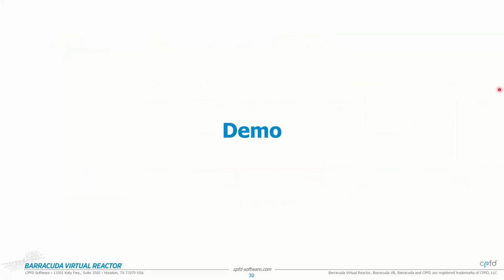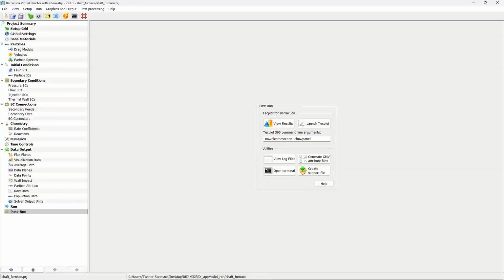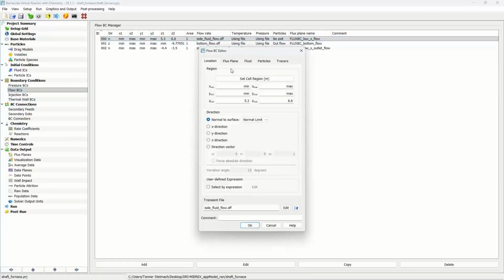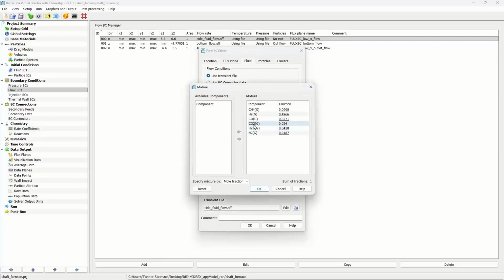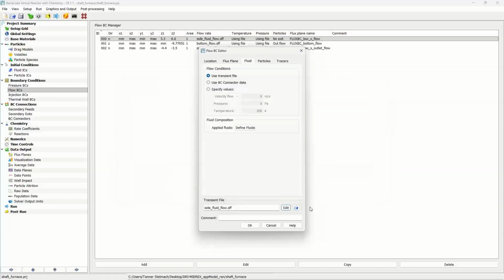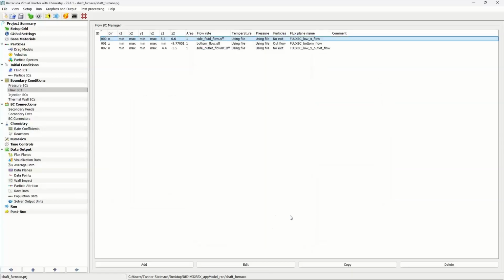Right, and I wanted to quickly show, for this system, in order to adapt the model we currently have on this application model post to operation as a shaft furnace, you could come here to this system and we can make adjustments to the actual composition. So for those tests, we use 100% hydrogen. This mixture mole fraction can be changed to 1. And you can also make changes to temperature for this reducing gas inlet as well as the flow rate. All right, coming back here.